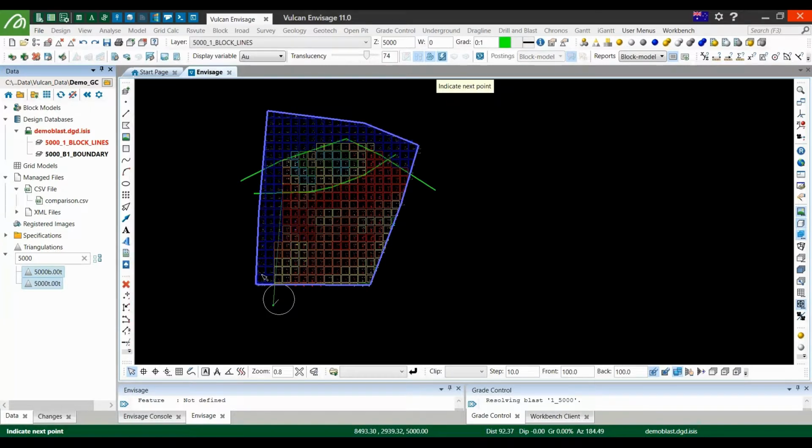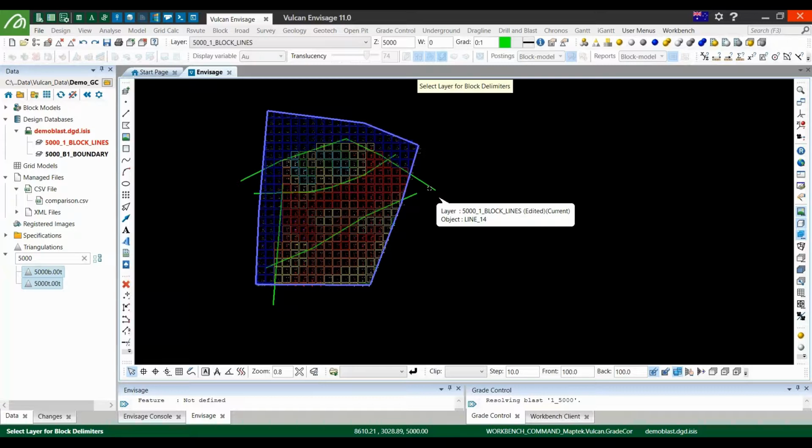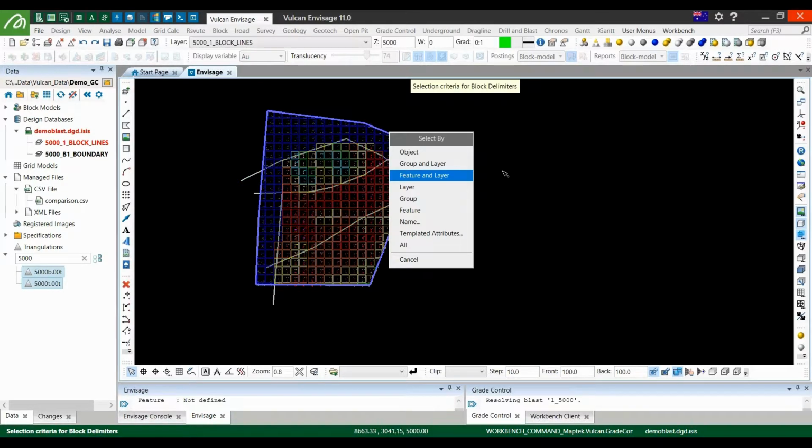I'll cut off the waste through here, and perhaps I've got a low grade area up through here. To help check how well I've done, I'm going to run the blocking process. So I'll create my grade blocks from these lines. You'll see one of the options in there is to use triangulations. So if you do have any angled trim blocks that things aren't vertical, you could use that. Or if you did have a fault coming through, you could pick a triangulation or give one of the lines an angle, but these are all vertical.